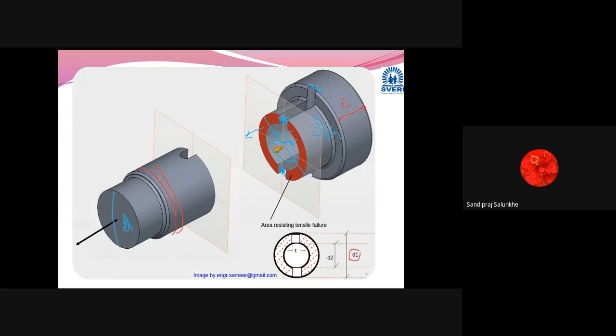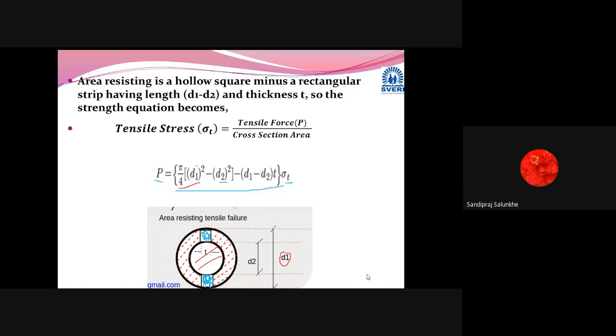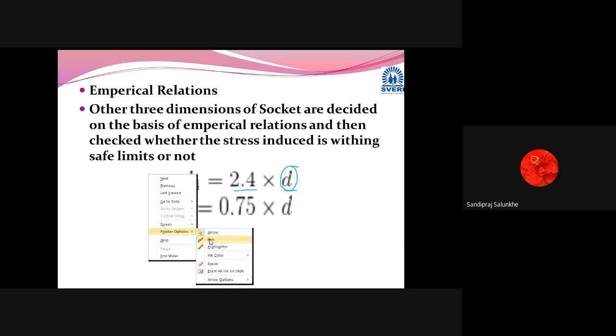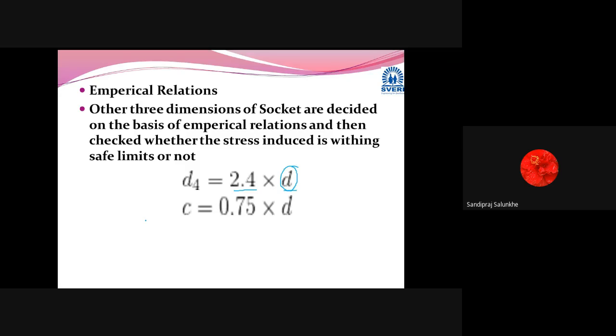Now the collar diameter is calculated by just one empirical formula, which has come from the previous experience of designers, from the design data book. One can also calculate that dimension with the help of experience. He can try a diameter equal to D1 only. Then he can slightly increase that diameter as D1 multiplied by some quantity, like 1.2, 1.3, 1.4, 1.5.